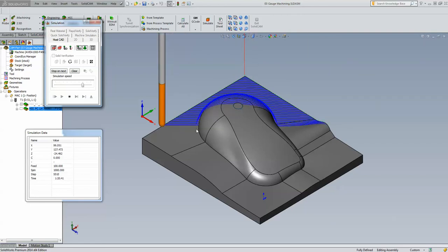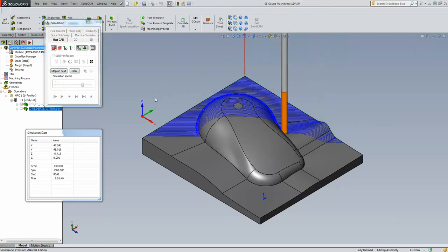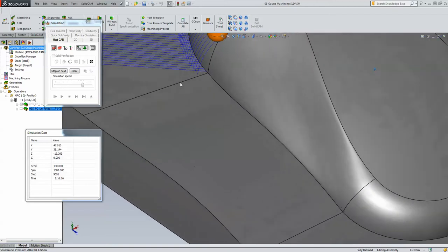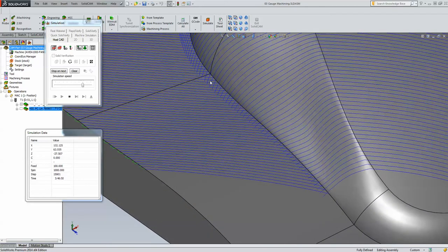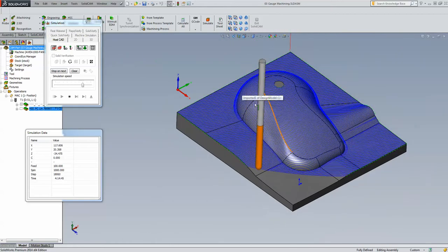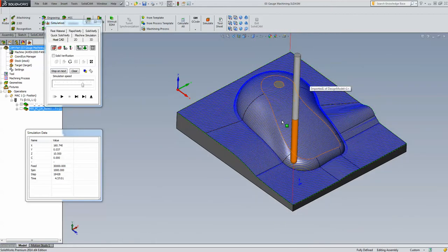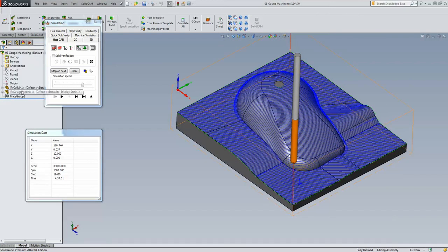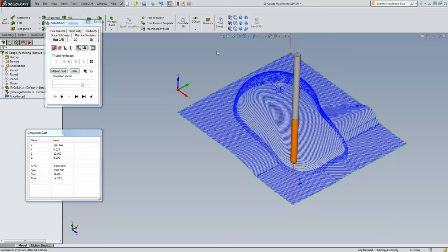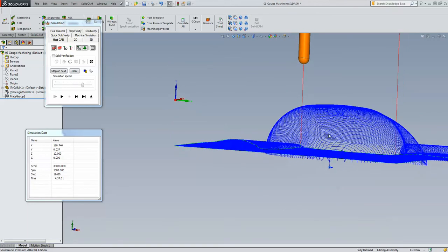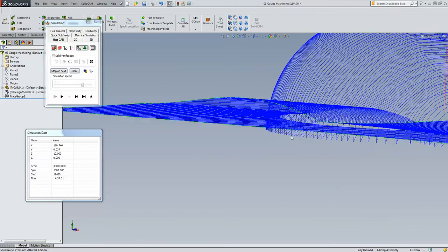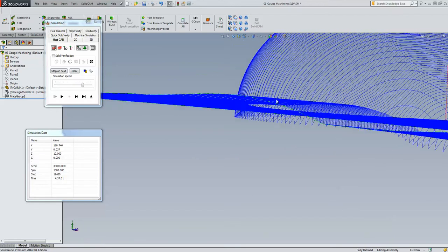You'll see it happening in a moment. You can see the following. It's actually doing something like this. It's going to the corners, then turns itself around in the material to go around that surface over there. Well, actually, let's hide the part itself. Let me just go over here and hide the actual component. If we take a look at the toolpath, you'll note if I look at the bottom, it's actually gouging into the material at the very bottom over there.